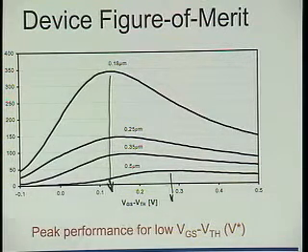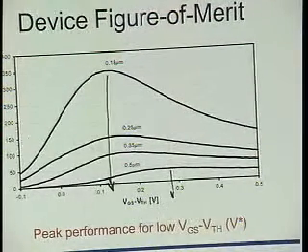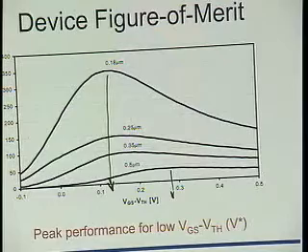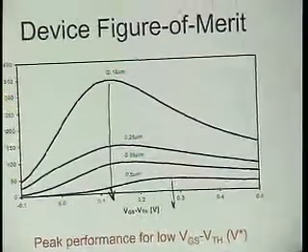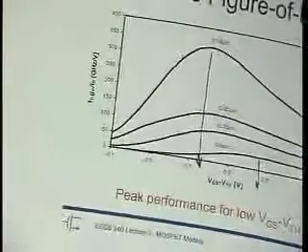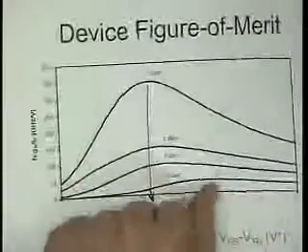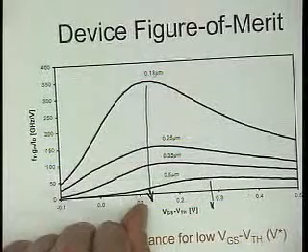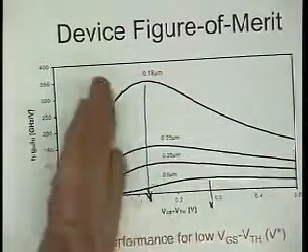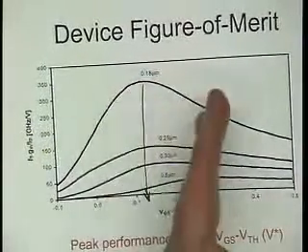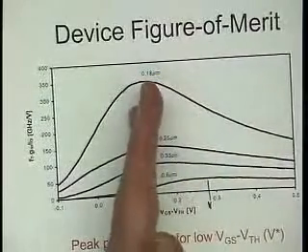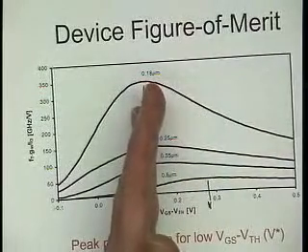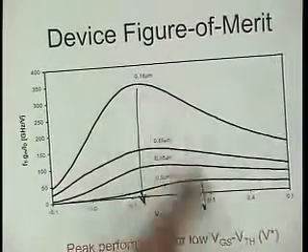As supply voltages shrink, as transistor dimensions shrink, at least we need less voltage to run our transistors, and we still can go faster, with more current efficiency. Actually, the current efficiency increases, because we are moving down here. And the speed we more than retain, because the reduction in this direction would normally make things slower, but the FT increases so incredibly much that this shift is more than compensated.